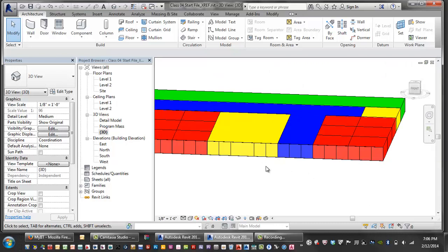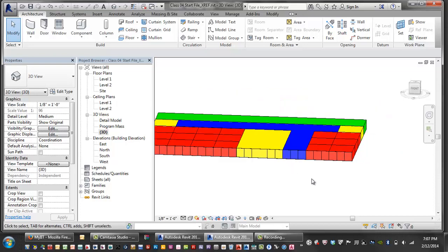Do you mind when I check the equality? Oh, yeah. If you go ahead and put the distance command and put it on one of the masses, you're going to be driving the mass then. So you want to make sure that you're only snapping to the grid lines and the reference planes, not the masses, when you do this.